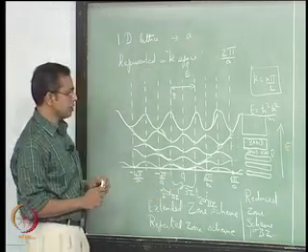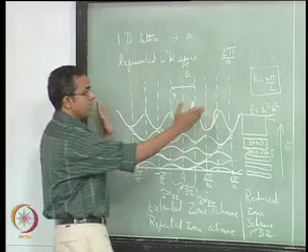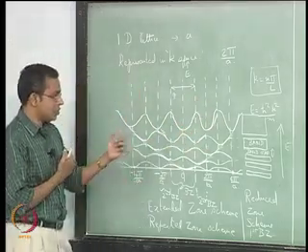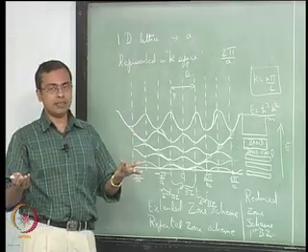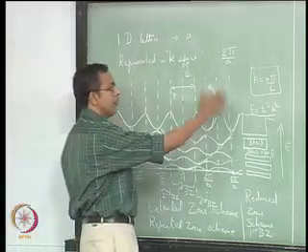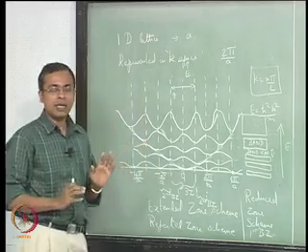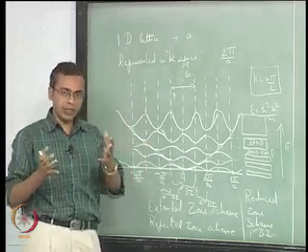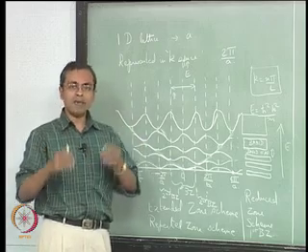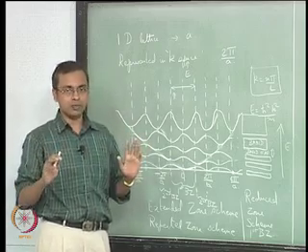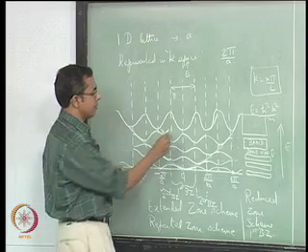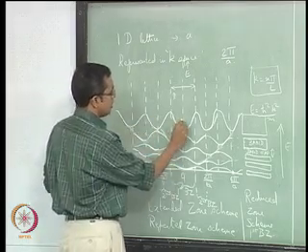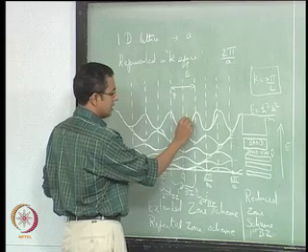In this I also wish to add that we have only shown the E versus k relationship, right. The other information that we have not shown here is where the Fermi energy is. These are all the values of E versus k that are permitted in the system. Depending on the particular atomic system, the particular material you have chosen, the Fermi energy may be at some particular value. So, I will arbitrarily say that, on this energy scale, the Fermi energy is here. This is just an arbitrary choice.